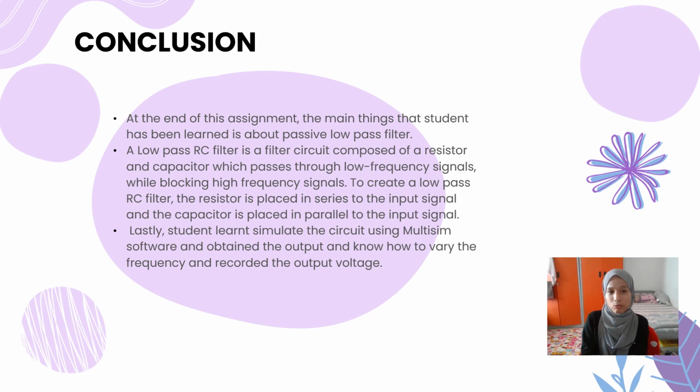After that, students are able to derive the transfer function and learn how to calculate zero and pole by using formula based on the simulation circuit. Then, students are able to calculate frequency based on the simulation circuit. Lastly, students learn to simulate the circuit using Multisim software, obtain the output, and know how to vary the frequency and record the output voltage.